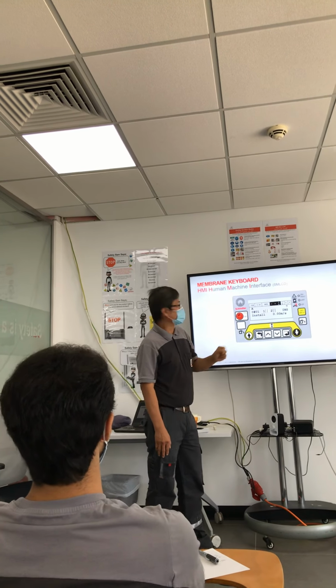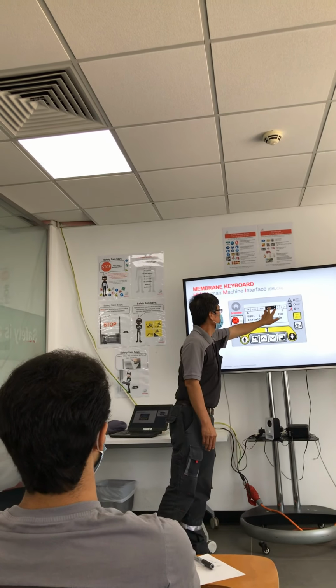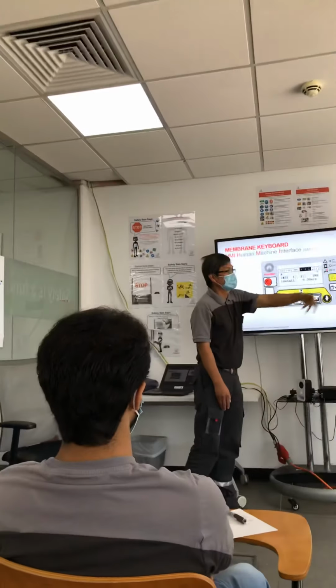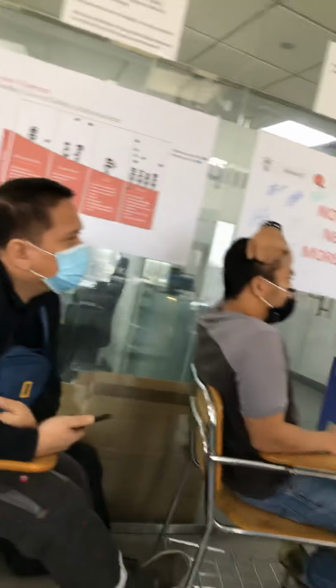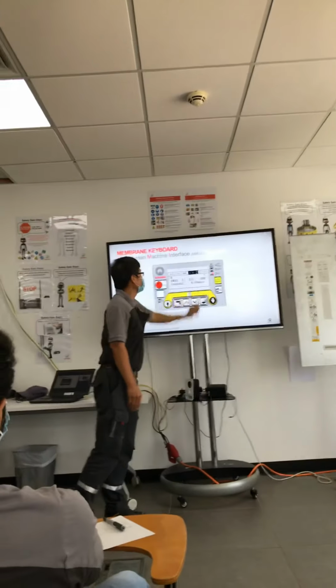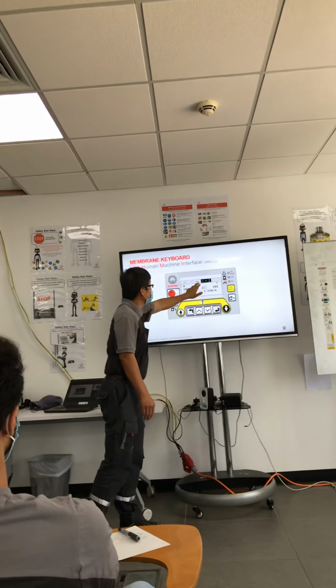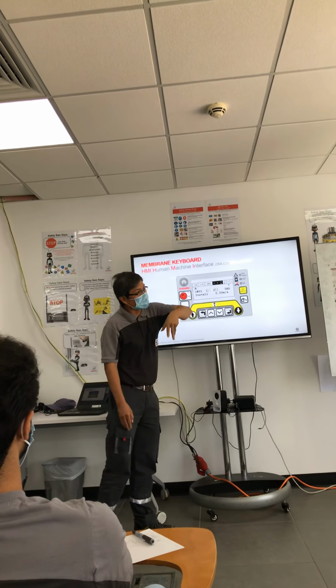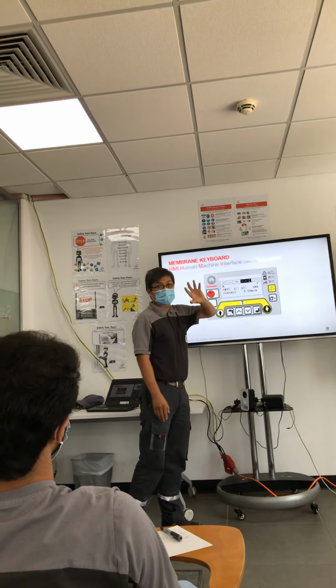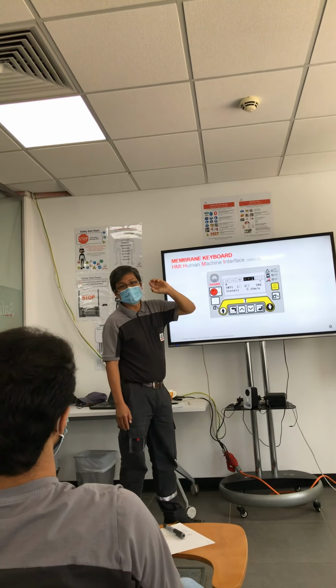The black one is okay, but this one is not okay. You can determine what safety circuit, what contact, the kind of other problems. Now this one is fatal. If there is a problem, this one is the indicator of the fatal. So you know now this elevator is not working.